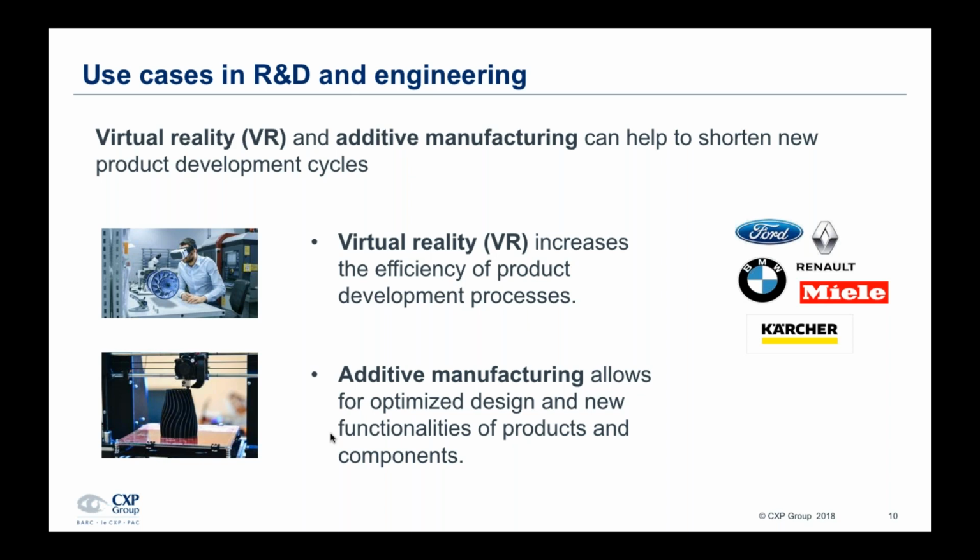And looking at additive manufacturing or 3D printing, this also will increasingly play a role in the R&D domain of manufacturers. And this is not only because prototypes can potentially be built faster and comparably cheaper. These new additive manufacturing technologies are in particular interesting as they allow producing products or components with optimized designs and new functionalities. So one major advantage of additive manufacturing is that it allows objects to be designed and produced in such a way that material usage and consumption can be minimized. This enables the production of lightweight parts, which is particularly important for the aerospace industry, where you'll find, for example, Airbus being a very early user of additive manufacturing technologies.